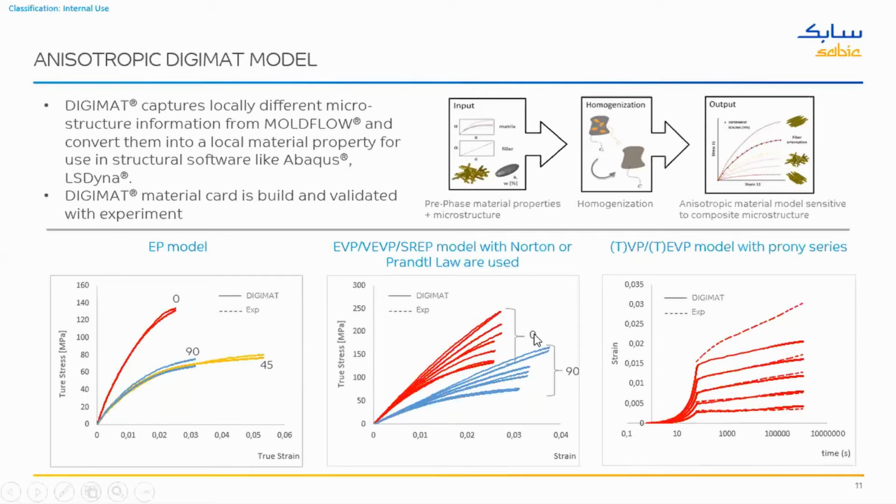Now here we have seen the comparison for the different strain rate values. One is for the 0 oriented tensile bars and the other is for the 90 oriented tensile bars. By far, for all these results, one could see that the 90 oriented stress-strain data is always on the softer side as compared to the 0 oriented tensile bars. And as a function of strain rate, we could also see a stiffening of the material response, which is very typically observed behavior with such material systems.